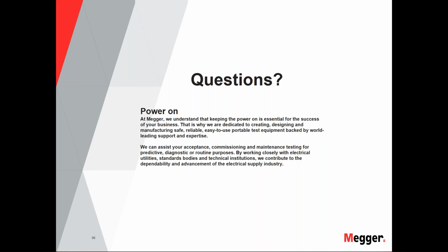It is not the usual practice, but some of the utilities do it in controlled scenarios. It is sometimes risky to stop the prime mover power completely and then stop the generator power, basically tripping the excitation power. Sometimes it can over-excite. Also, it is possible it can go into the capacitive mode, basically called leading mode. So that's a risk for the generator, but very well-controlled and very knowledgeable, well-trained people can do this process.